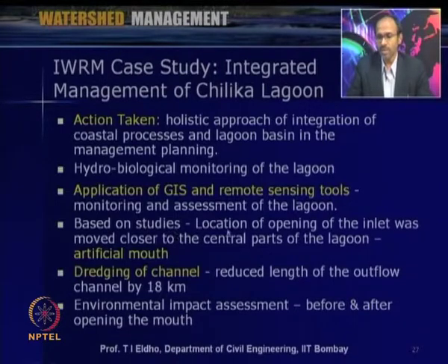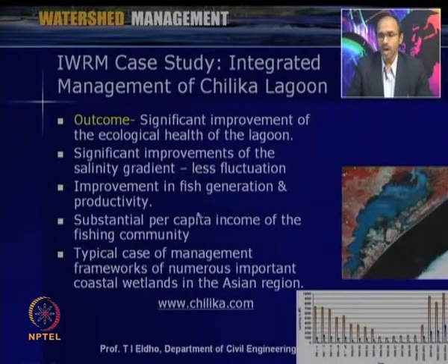Based on various studies, the location of the opening of the inlet was moved closer to the central parts of the lagoon, and an artificial mouth was generated, and dredging was done for the silted channels and areas. And then also the environmental impact assessment has been done before this project has been implemented and after the project has been implemented. So some of the outcomes of this project are listed here.